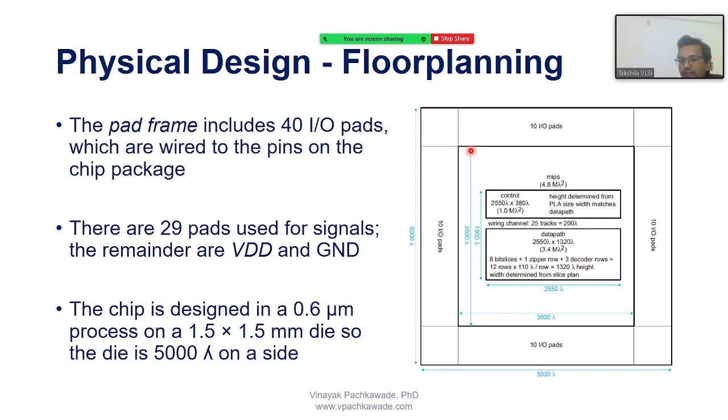Now inside the processor, I told you there is microarchitecture. Microarchitecture would be Pentium, whether it is Pentium processor, Core 2, or Core i7, etc. So in that they defined which logic is sitting where. So here they are saying that here is the logic for data path. Here it may be a memory, ALU, etc. Here they have defined the control and the controller. So for this also they have estimated the dimension. You see 2550 lambda, 1900 lambda, etc.